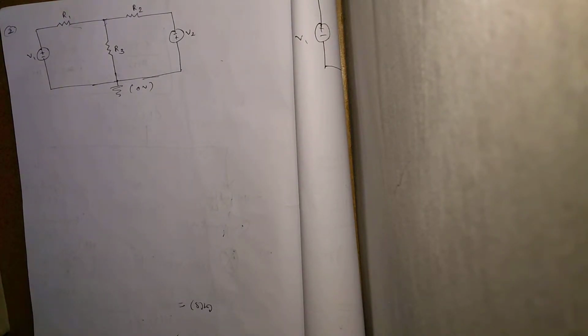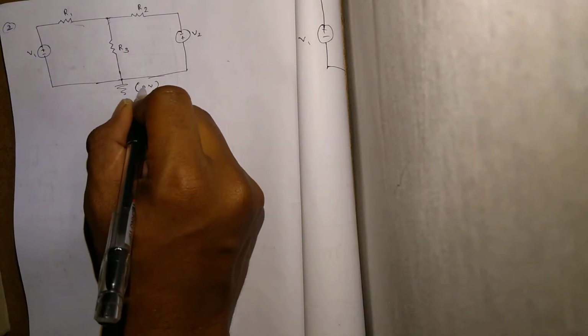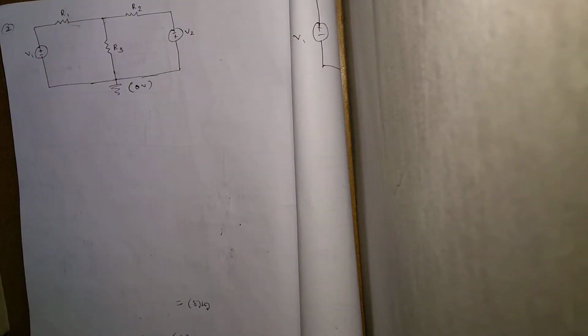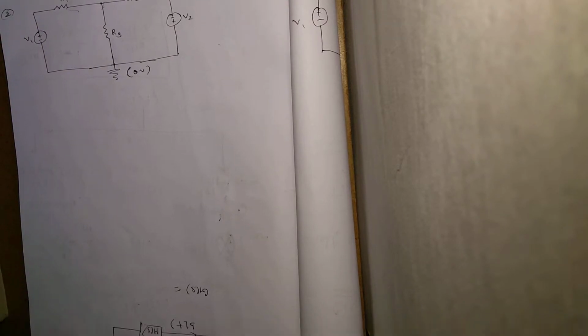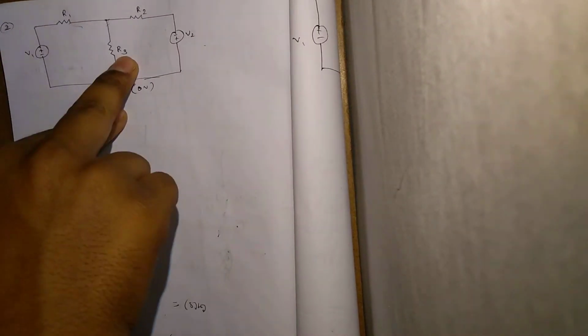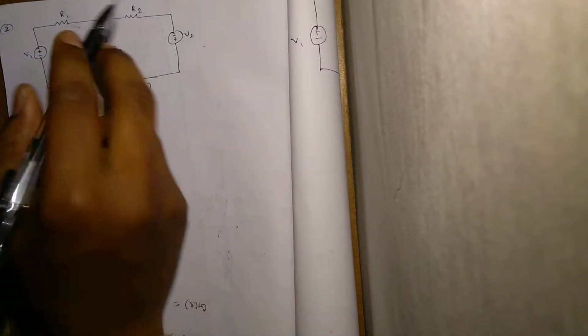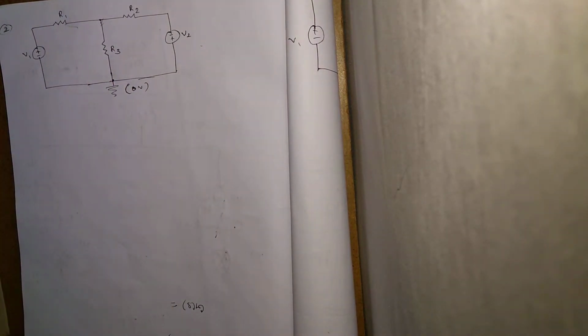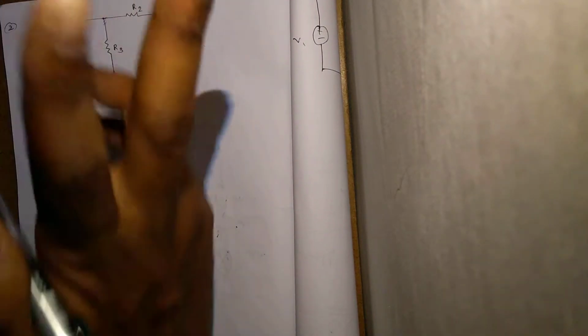So you know the standard procedure for solving any network or circuit by using nodal analysis. There is a three-step standard procedure. One is selecting a reference node, and my reference node will always be ground, that is 0 volts. The second step is assigning voltages for the other remaining principal nodes. In this example, I have only two principal nodes. This is one of the principal nodes and this is the other principal node. You know the meaning of principal node, and for this example I just have two.